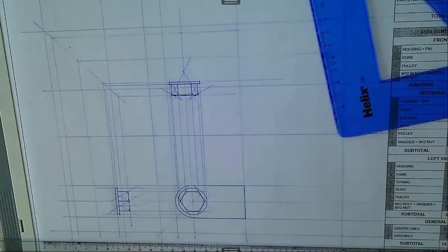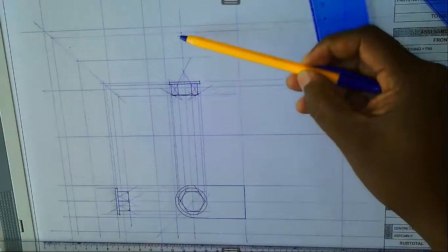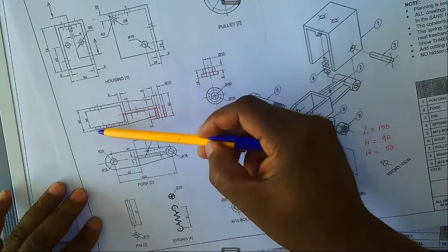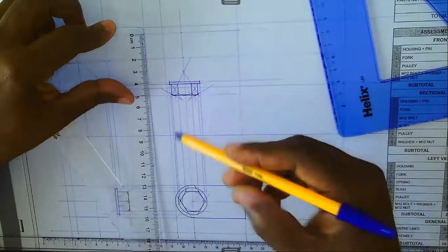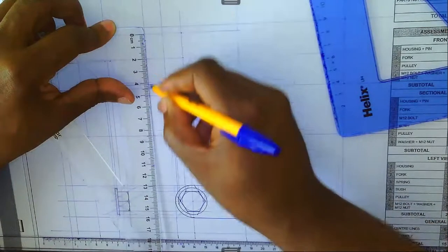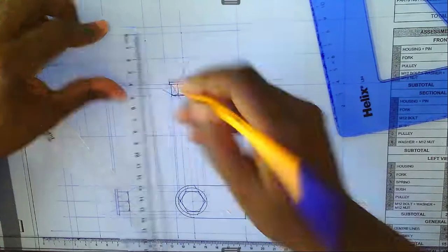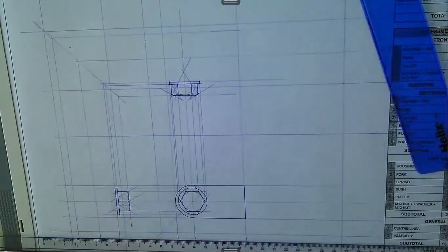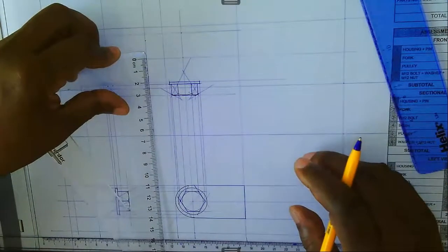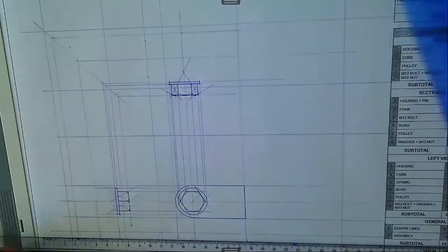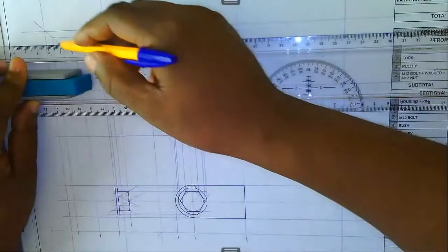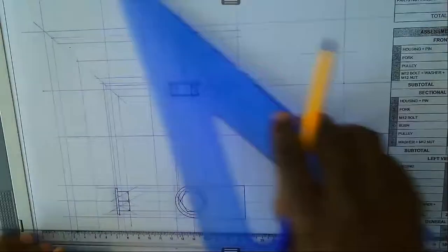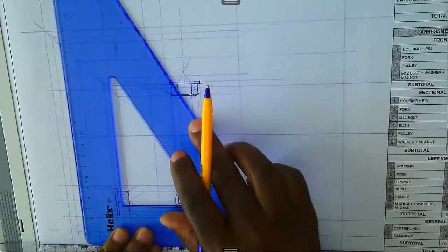All right, okay. Now, we may also need, now we know that from here to there, that's the fork, okay? Right, and what is the size of the fork? Right, so from here to there it's 40, but from here to there is 30, which means either side is 5 millimeters, 5 millimeters, right? We can just measure 5, we mark like that. Also measure 5. That's correct, which is that. So I'm going to project this, right? And also do the same this side to there. Take this one up.